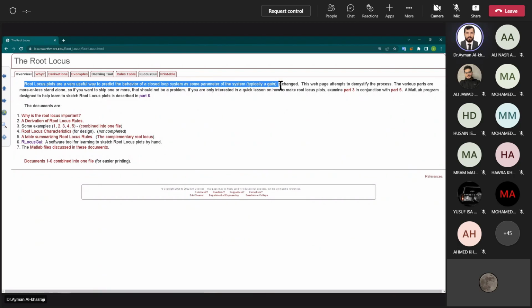Okay, but when we change the gain, what we are taking is the open loop. So don't close the loop. If I give you GH, don't take G over 1 plus GH and then find the roots on the plot. No, you take it directly. This is also explained. So it's the method to find the closed loop roots from the open loop.